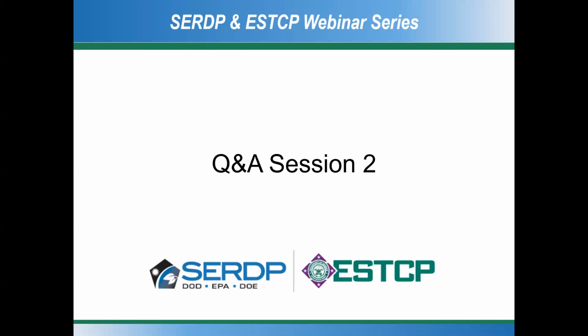The only guidance I think our course will cover is you have to select open system. We do discuss a lot on the UFC, Unified Facilities Criteria, and Unified Facilities Guide Specifications on the requirements for the DoD project. Again, most DoD projects require very general open protocols. So we can probably provide some examples of the product, but we don't mention specific features or technology regarding the manufacturer product. We just suggest you have to comply with specific open protocols.